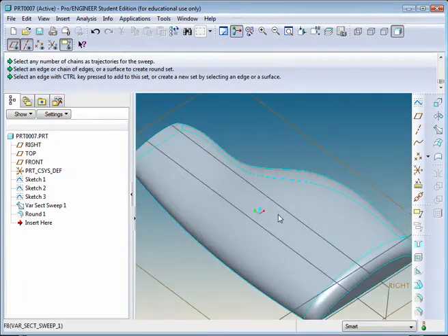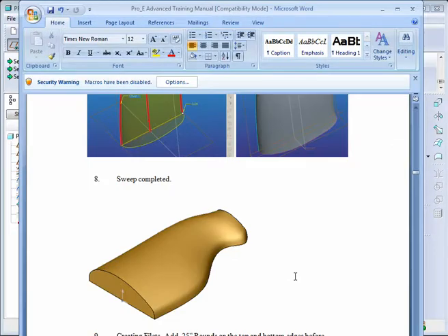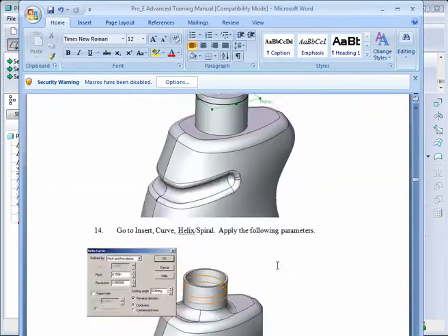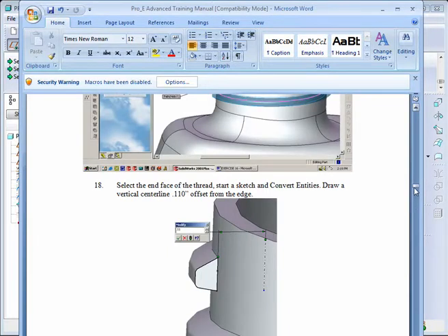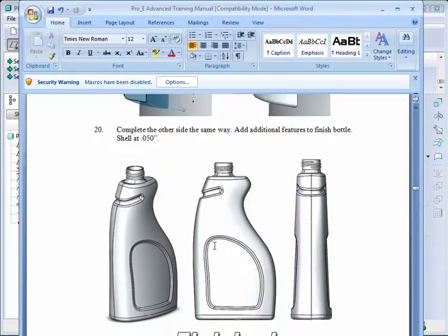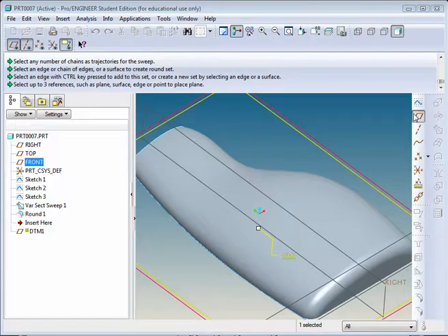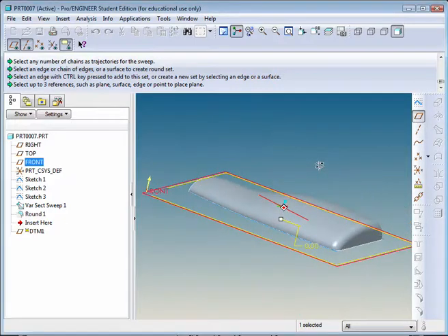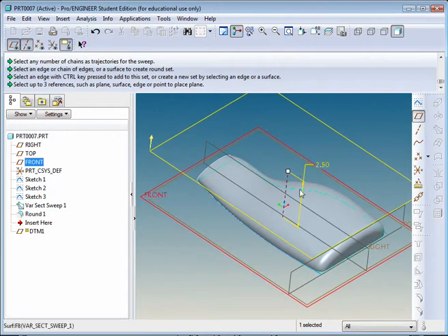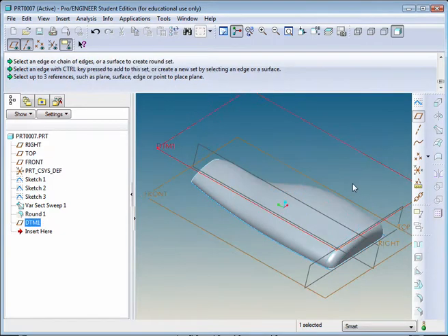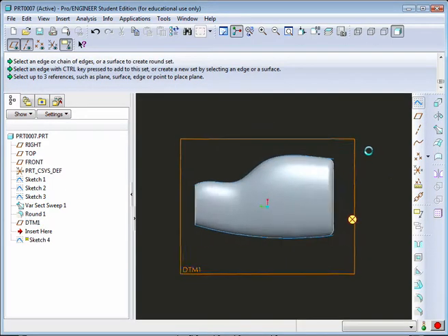Okay. Now to get a contour on this, similar to what we see in the book, scroll down here, we actually have a label recess. To add that, I don't actually have that in the book, but what you can do is take the front plane and go to the plane tool here. It's already selected as an offset. You could just drag it up above the surface. Any height will do. And now we could select and start a sketch on that.